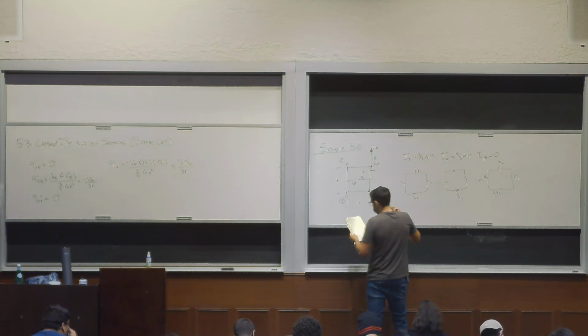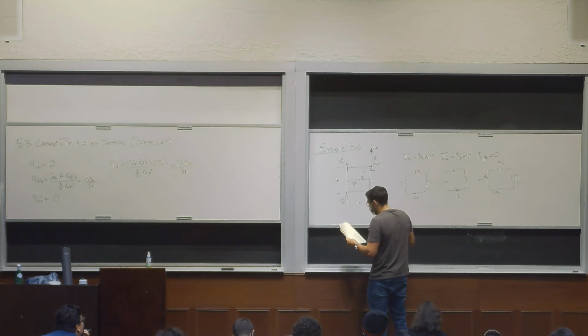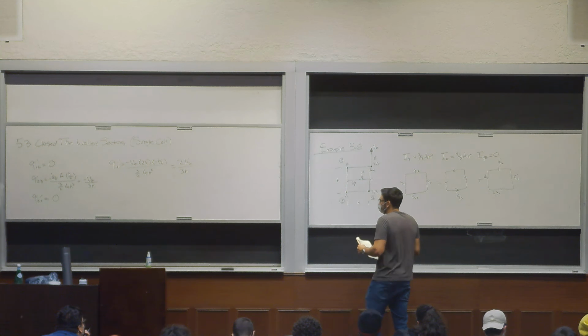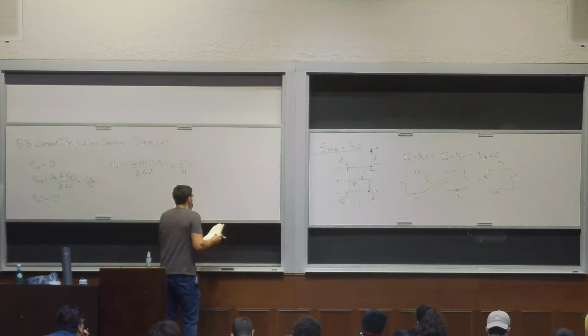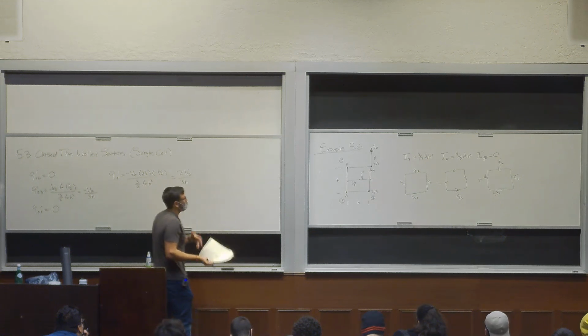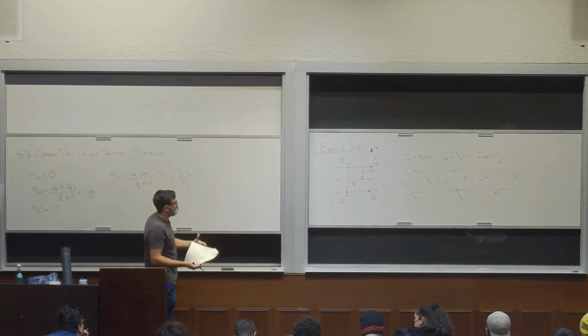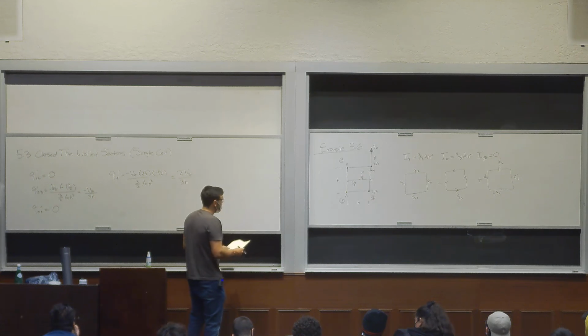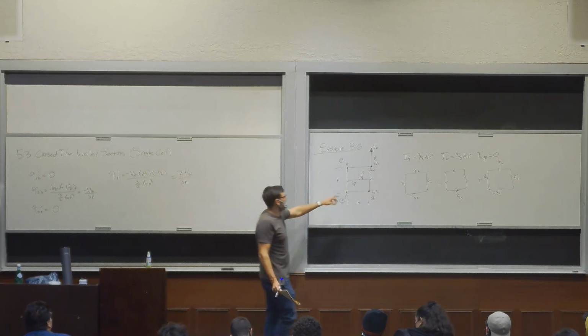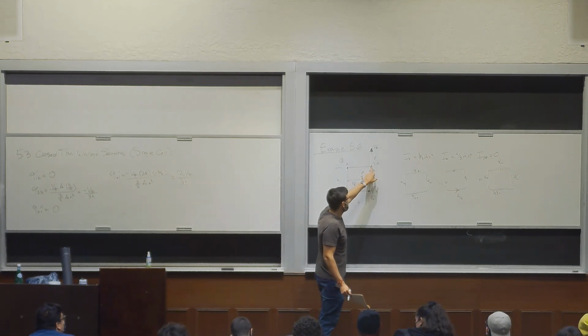I don't think they give us a value, but it's important to know where it's applied. So now to find Q naught, the last step is basically you got to set the moments generated from VZ about a certain axis equal to the moments generated by the shear flows about that same axis. In this case, we choose this spar to be the axis of interest.